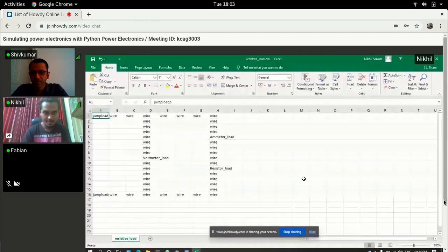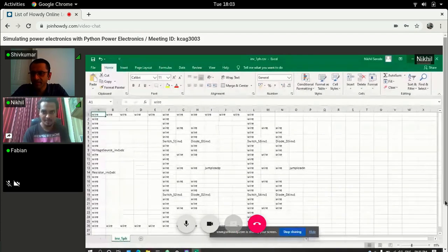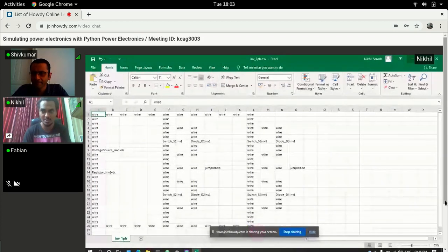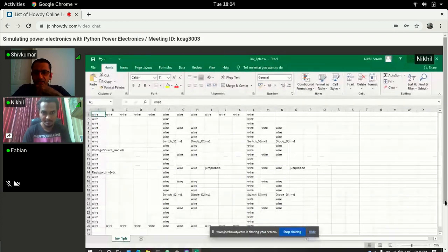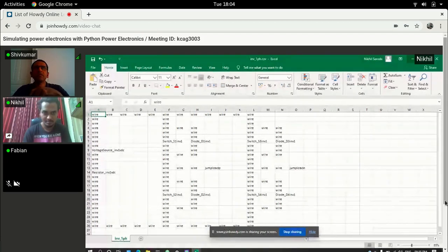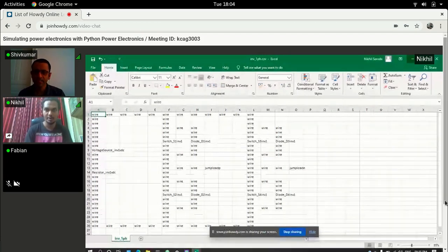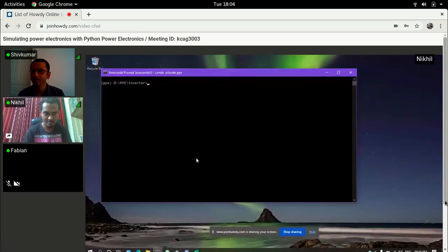First and foremost, I'm assuming you are using a 50 hertz fundamental frequency. Yes, 50 hertz and 20 kilohertz switching frequency. Okay. Would you like to run this program and show me the switching waveform? For now, the simplest way I can suggest to verify what you will get is by connecting an LC filter.